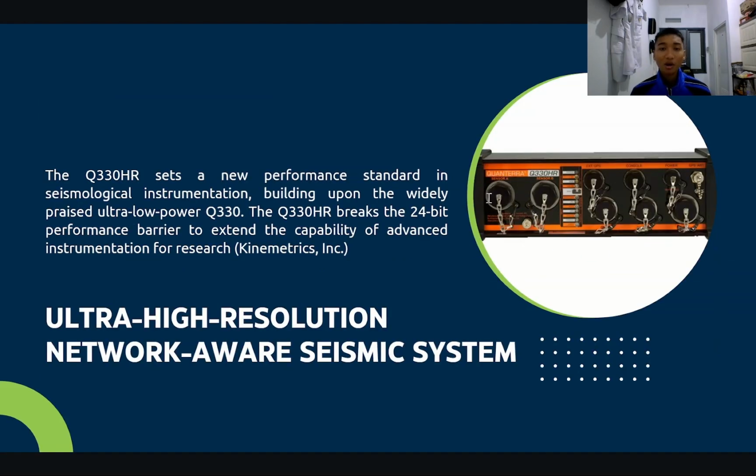Next is the clip level, or the maximum signal limit that can be recorded before clipping. The STS 2.5 can handle ground vibrations up to 13 millimeters per second at frequencies up to 20 Hz. For frequencies above 20 Hz to 50 Hz, this limit undergoes linear derating, or a linear decrease, to 5.3 millimeters per second. These specifications ensure that the instrument continues to record complete data even when there are strong ground vibrations.